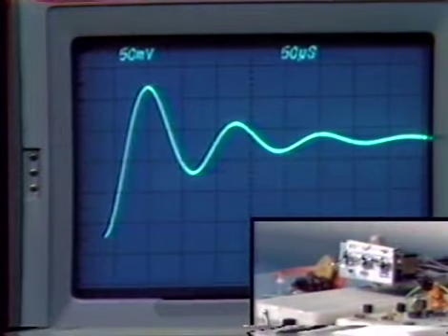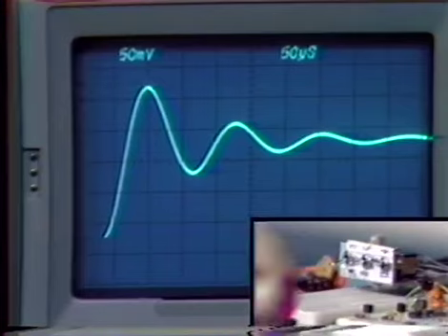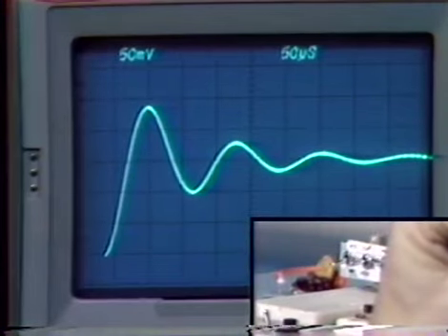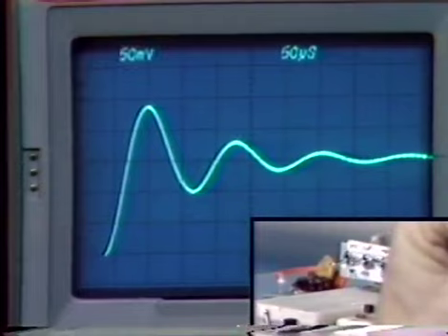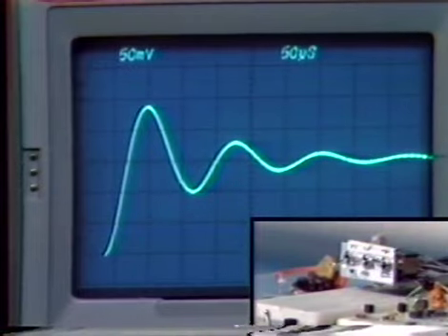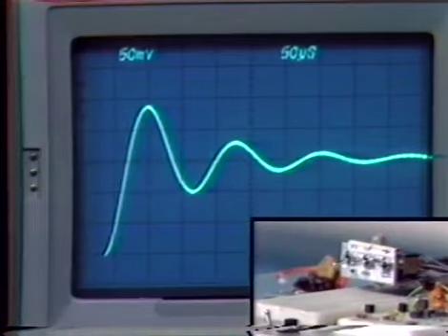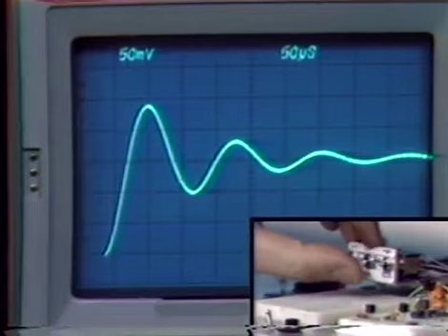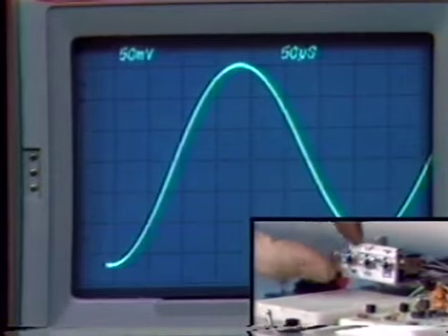Let me slow the generator. But now we have considerable overshoot. We're putting in a 3-division step and we're getting 60% overshoot or something like that. Very prolonged transient, very poorly damped. Let's try it just one more time. That was with a 10 kilohertz pole location.